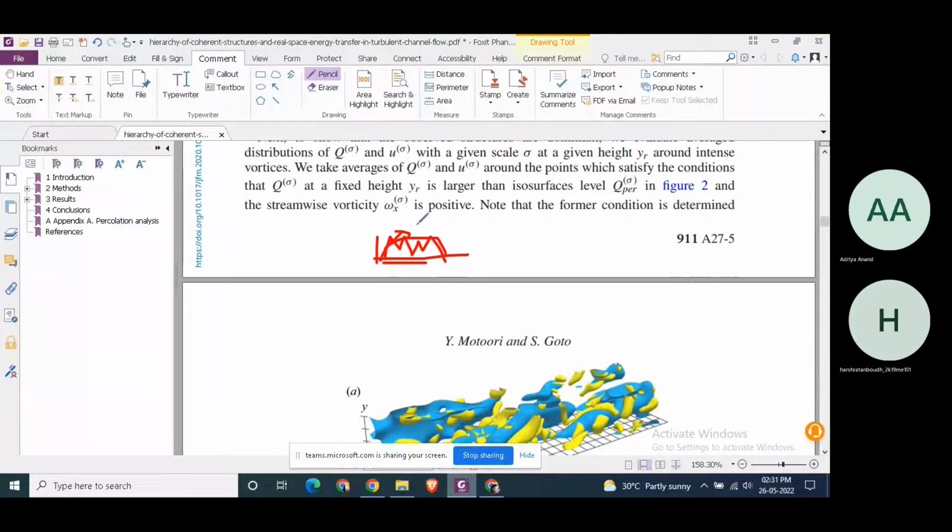If you remember the example about two superimposed sinusoidal waves that I had talked about, take a sine wave of one frequency, and on top of that you add a sine wave of frequency 5 times the earlier one. What you will observe is a sine wave which rides on top of the lower frequency sine wave. If you average this signal over a long enough time scale, larger than the wavelength of the largest sine wave that is there, you'll get a constant mean velocity. But the fluctuating part will have contributions both from the large wavelength sine wave and the smaller wavelength sine wave. Okay, I get it.